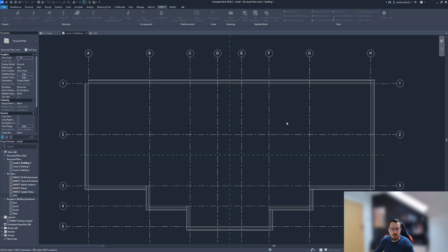Ignore this warning for now. That's because once I divide the walls into appropriate sizes, the lifters will automatically come. There is intelligence to automatically add them once we edit that, so the lifters are there, and we don't have to worry about it too much. And now Impact does all the geometry.